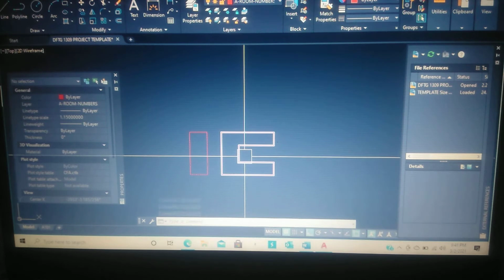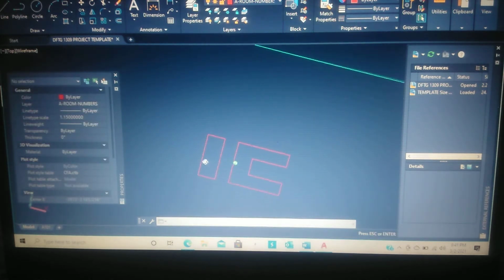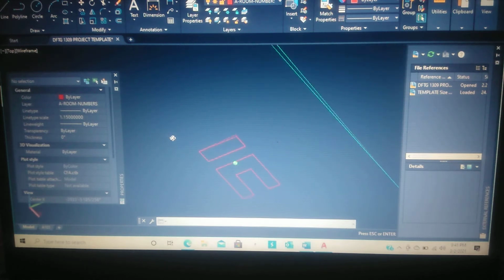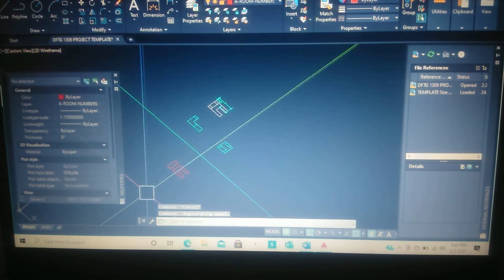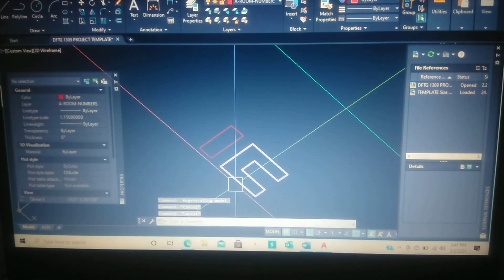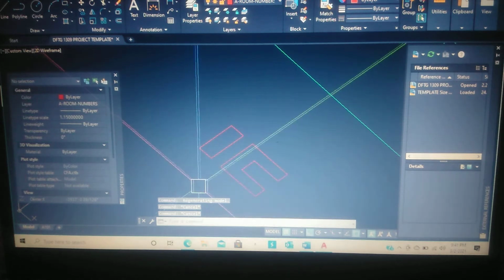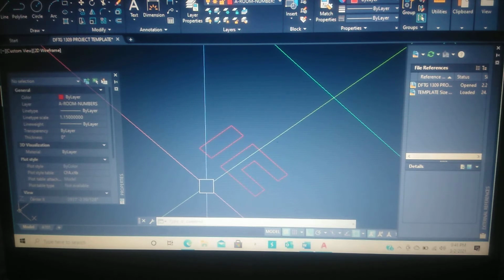You want to hold down Shift and push the scroll button down. This will activate the orbit command, okay? So we want to go to a 3D view. So orbit, however you feel, whatever you feel comfortable with. So now that we have this orbited, we know that this portion, as we look at the side and the front drawing, is going to be 2 feet.